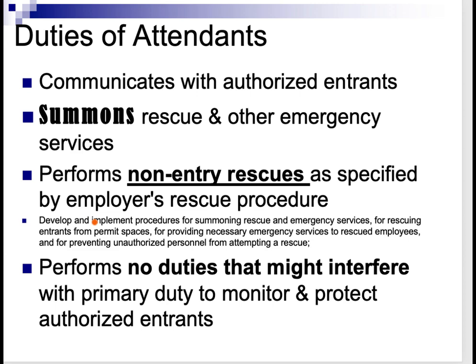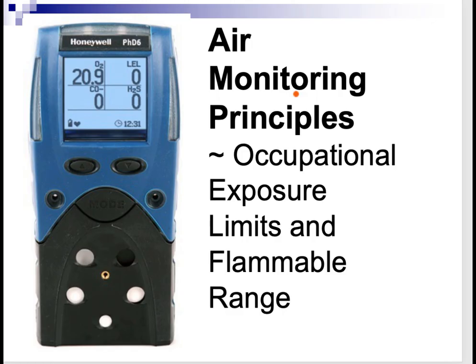You should perform non-rescue duties, which means you implement your plan, and as long as you don't have to enter the tank, or whatever the confined space is, although I always think of a tank, you can aid in the rescuing of the person who may have had some kind of incident or accident. And you're not allowed to perform any duties that would take you away from attending to the person who has